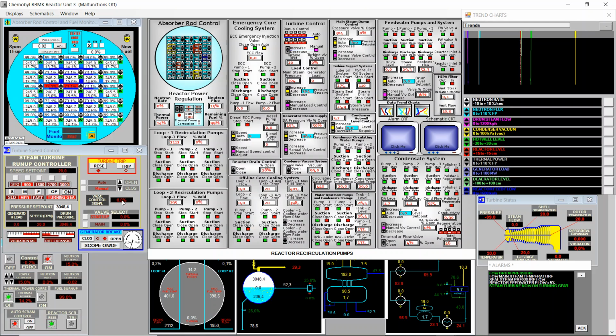But I know by experience that to keep the turbine at 3600 RPMs without synchronizing to the grid or connecting to the generator, we need around 5% of opening of this valve. So this gives us already some information. When we are approaching this terminal value of speed, we will start closing the valve to have an asymptotic value of 5%. Okay, we have already many warnings disappearing.